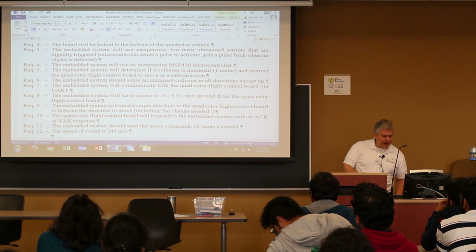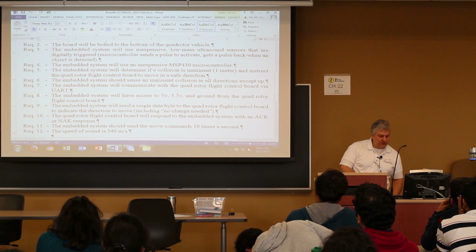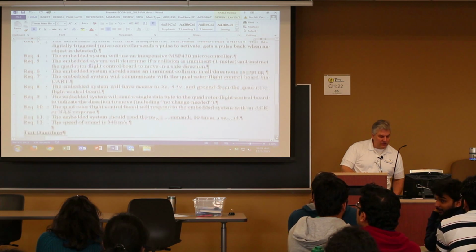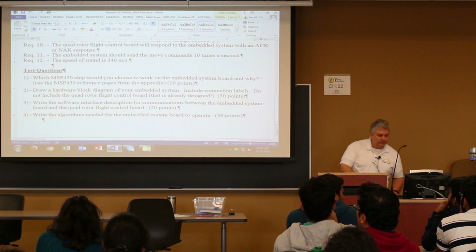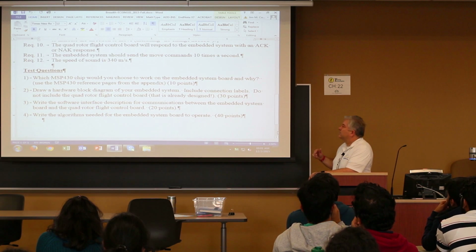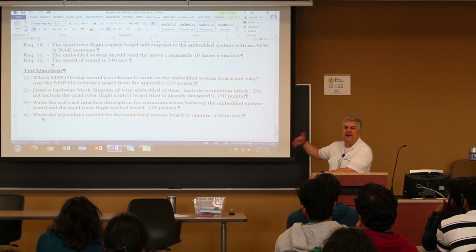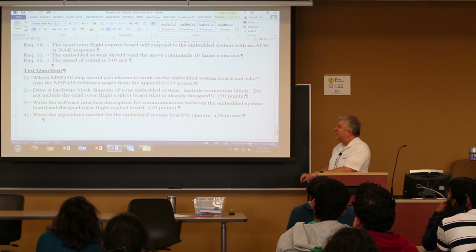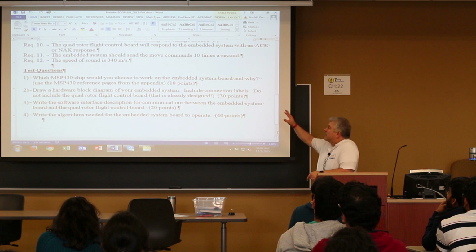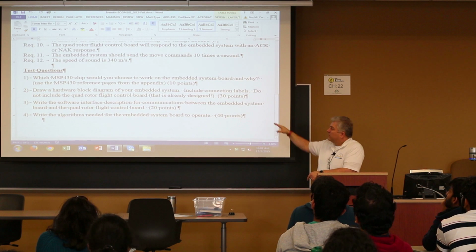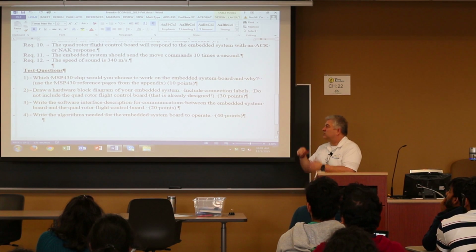So the next step, I ask for some specific deliverables. The deliverables that I'm going to ask, and we're going to talk about this a little bit, is which MSP430 chip would you use on the board and why? And then I have a reference page that I'll provide, and I'll talk about the steps of why you would do one thing or another. Draw the block diagram of your embedded system, including connection labels, which also means power. All right? Write the software interface description for communications between the boards.